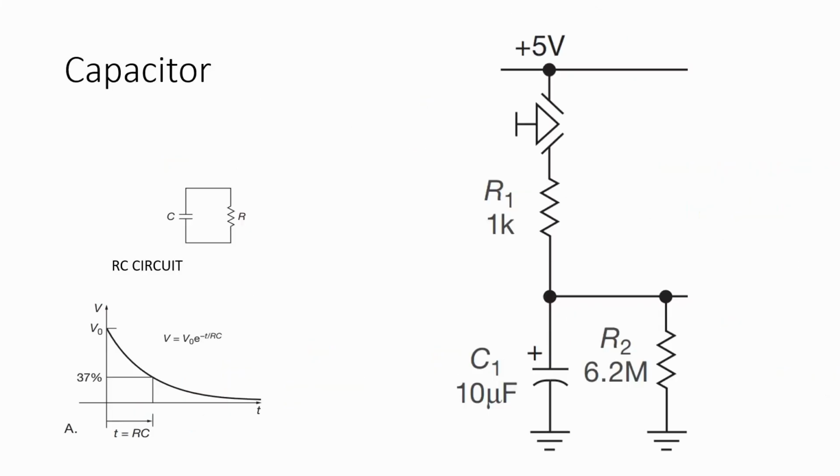So now let's look at the two individual bits, the potential dividers, in isolation. This is the first part of the circuit which controls some of the timing, in that we have the capacitor here and we have the dissipation resistor. When the switch is open and the circuit has been sitting there for a long time, the voltage across the capacitor will be equal to 0, as it will be discharged through this resistor and a little bit through the comparator or the op amp. But let's ignore that for an ideal case.